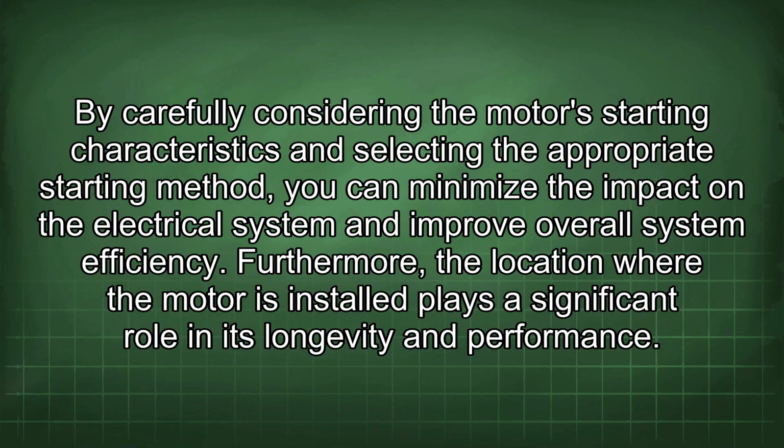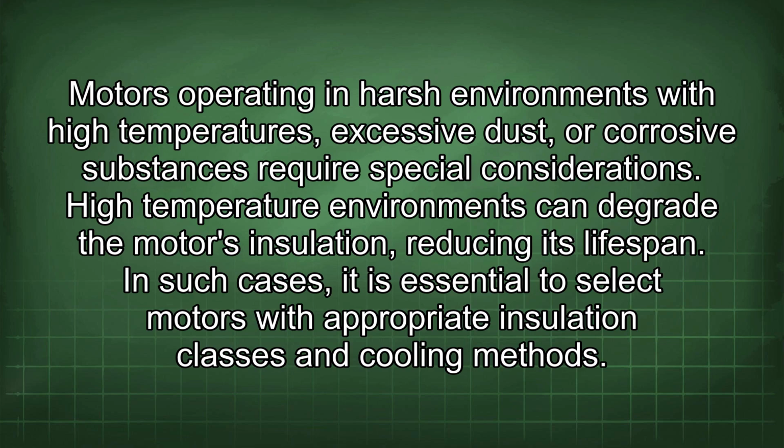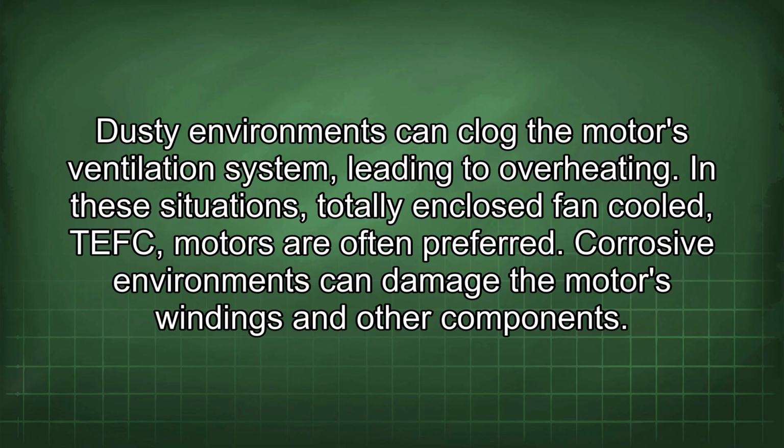Furthermore, the location where the motor is installed plays a significant role in its longevity and performance. Motors operating in harsh environments with high temperatures, excessive dust, or corrosive substances require special considerations. High-temperature environments can degrade the motor's insulation, reducing its lifespan. In such cases, it is essential to select motors with appropriate insulation classes and cooling methods. Dusty environments can clog the motor's ventilation system, leading to overheating.